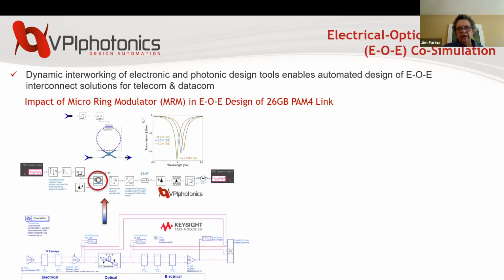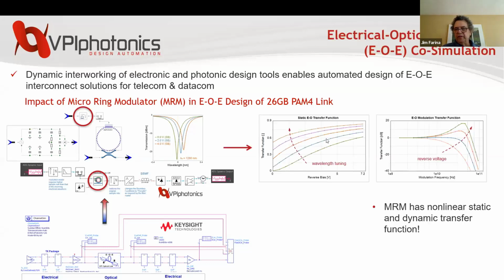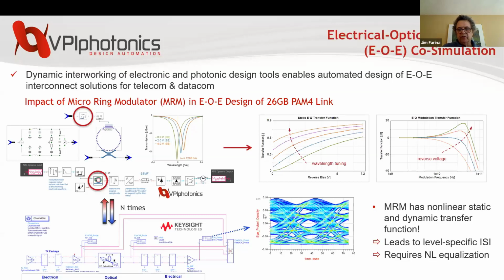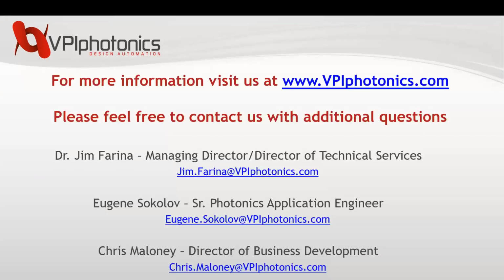And so you can look at details of the characteristics of the micro-ring modulator, and produce all kinds of characteristics using the actual driver models. This can be called many, many times, so you can look at some more dynamic situations with ADS. ADS also has a really nice interface for a TDECQ measurement that's pretty sophisticated, and I'm pretty sure they keep it up to date. So that's another way to do TDECQ. Okay, well, thank you. I hope you get something out of this. You can take a device and the device model that you have, promote it into a system, and do some pretty sophisticated modeling, analysis and optimization using a full system.